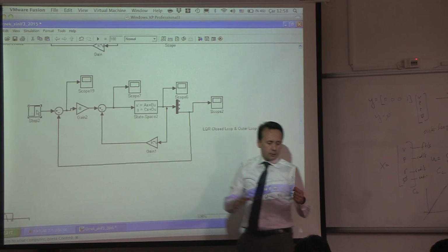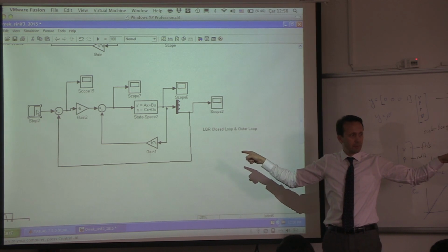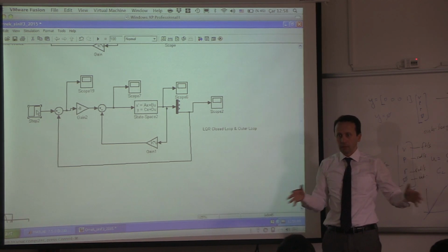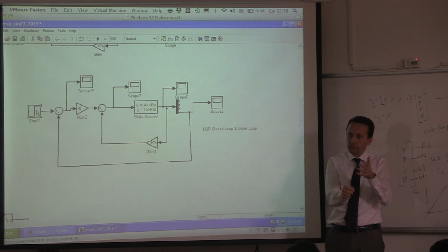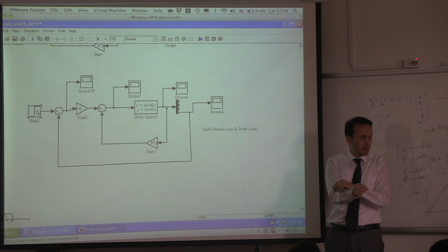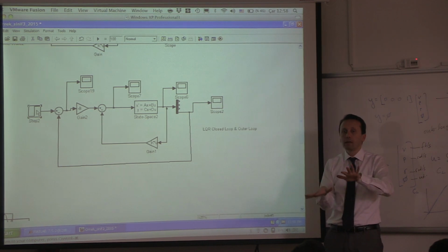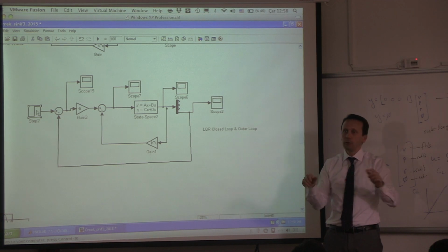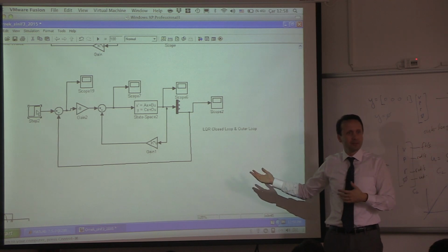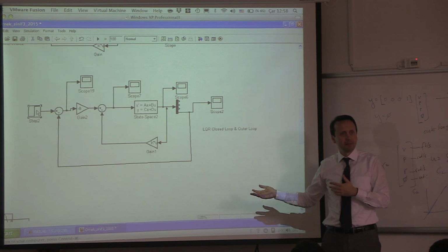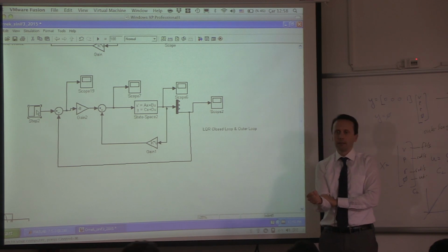Okay? So the pilot control will no more be connected to the ailerons. It will be connected to the computer. And the computer will only get the input of 30 degrees, 60 degrees, whatever, 10 degrees. So the pilot will be controlling effectively the roll angle. The pilot will no more be connected to the ailerons. The aileron is moved by the controller, by the autopilot. The pilot will only do that, and the aircraft will go to that.